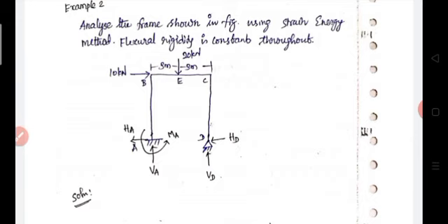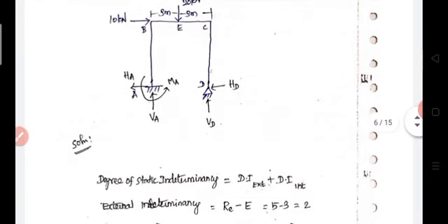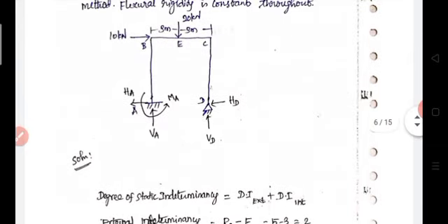In the fixed support we already know it resists both translation and rotation, therefore it has three reactions. In the pin support only translation is restricted, therefore two reactions. So the number of unknown reactions will be 5. The number of available equilibrium equations is equal to 3. Therefore external indeterminacy is equal to 5 minus 3, equal to 2.